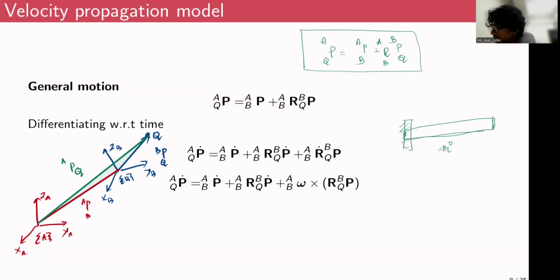I'll call this joint I, whose axis is pointing vertically upward, so that this link can rotate about this vertical axis, maybe theta I. As per the DH convention, we always have a frame of reference attached to the proximal end of a rigid link.